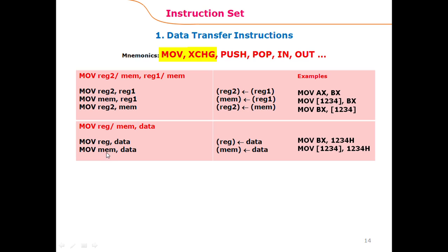And then there is the other form of instruction where the immediate data is moved or stored at a memory location, unlike the register which was used here. So the data is transferred or moved to the memory location. So here 1234H is the immediate data, and this immediate data is stored at the memory location of the data segment addressed by this address. So what happens is that a microprocessor first calculates the physical address of the memory destination where this data is to be stored. The address calculation begins with taking the 16-bit value from the data segment register, shifted by one hexadecimal digit, and then this offset value is added to that 20-bit value, and a 20-bit physical address or memory address is calculated. So this 16-bit value 1234H is stored on that memory location.